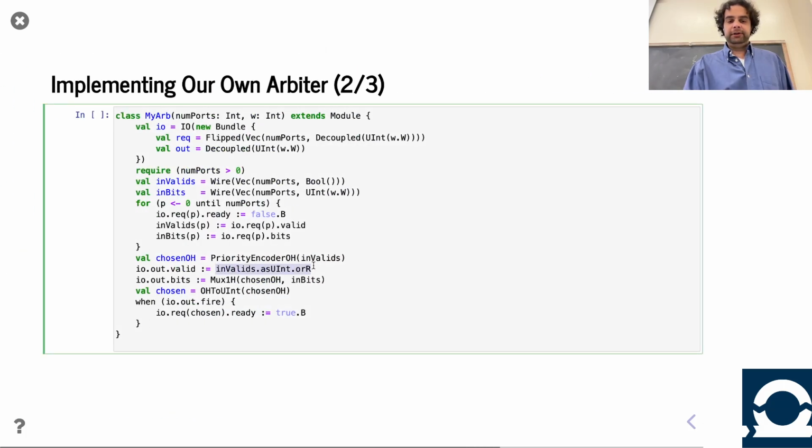So this is one thing I haven't covered yet. It was on the Chisel cheat sheet if you were looking closely. Dot OR big R. So it's OR as in a logical OR, and then the big R stands for reduction. Reduction is something that happens when you have many things coming down. So given, in this case, n wires, it just ORs them all together. Unbeknownst to us, that could be one massive OR gate. It could be a bunch of pairs of OR gates in a tree. We're not specifying that. We're giving the tools a little freedom on that. But yeah, it's doing an OR reduction for that.